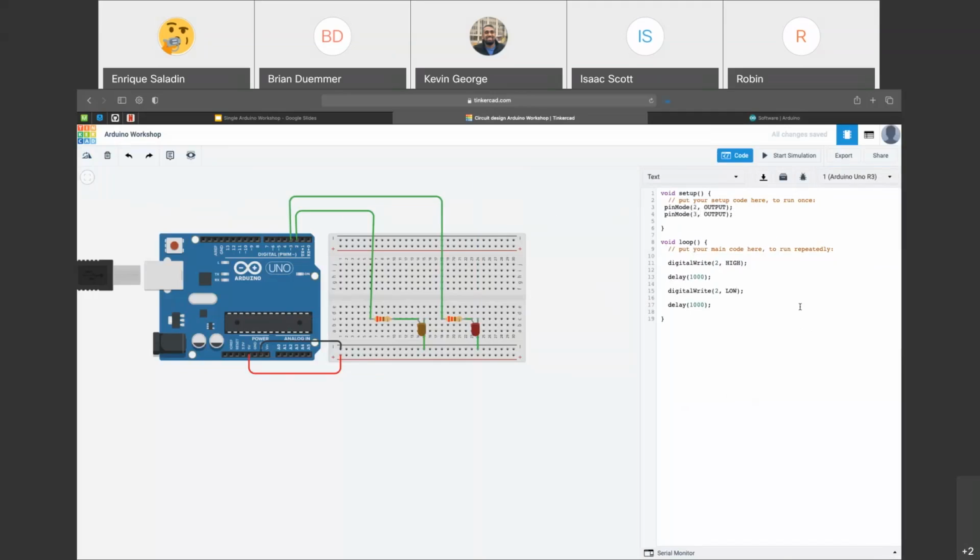And let's modify this piece of code so that once our first LED turns off, that second LED will turn on. So we're going to call our digital write function again to be 3. And let's make that value high. I'm going to put another delay on this. And let's make it turn off after this. Low. Put one more delay function to make this work seamless.